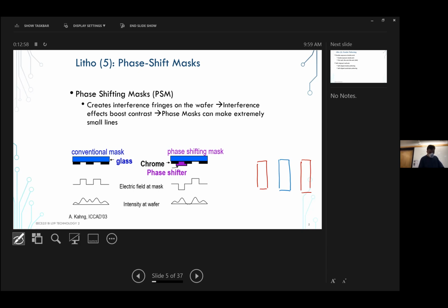Now I would like to add a transistor over here. Which color should it be? Or some feature over there, assuming that I'm allowed to have that direction. Which color should it be? Because you have to alternate colors so this doesn't come out on the projection.